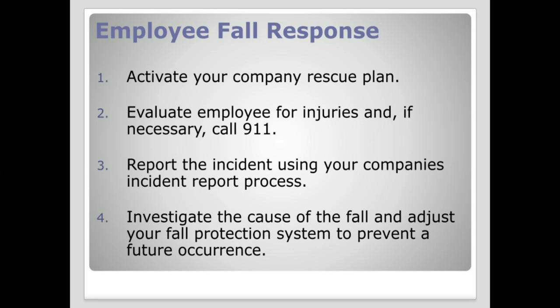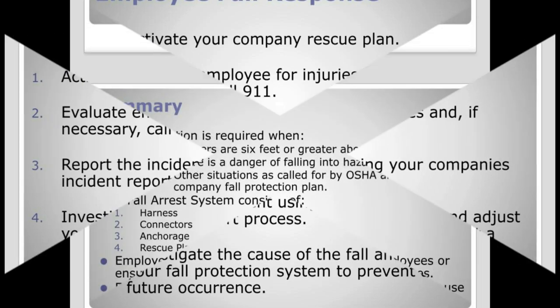2. Evaluate employee for injuries and, if necessary, call 911. 3. Report the incident using your company's incident report process. And 4. Investigate the cause of the fall and adjust your fall protection system to prevent a future occurrence.